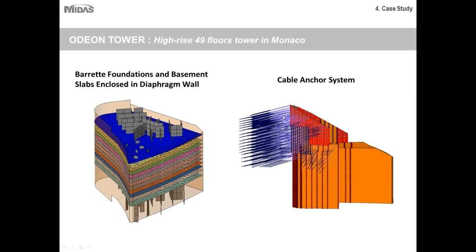So the retaining system and the adjacent buildings are closely monitored in terms of induced movements. The displacement fields predicted by this model were instrumental in defining the threshold values and action values, which allow for early detection of warning signs and timely response to any type of geotechnical hazards. For this presented case, a satisfactory understanding of soil structure interaction, in other words, how seismic loading would affect the foundation itself, and the way the retaining system fulfills its roles, can only be gained through 3D numerical analysis.